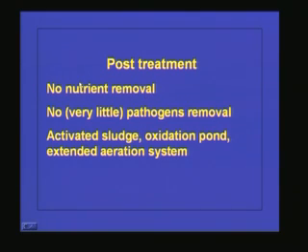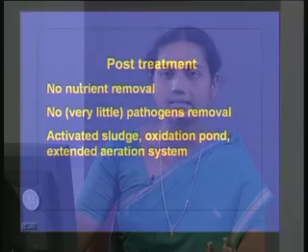Now, whatever we were discussing till now about the anaerobic treatment systems, in most cases these cannot be used as a single treatment process for meeting the effluent discharge standards. The reason is, the anaerobic process will not be able to take care of the pathogens or the microbial concentration present in the wastewater. It will be getting reduced only 1 log order or 2 log order. So we have to have a proper post treatment unit to take care of these things.